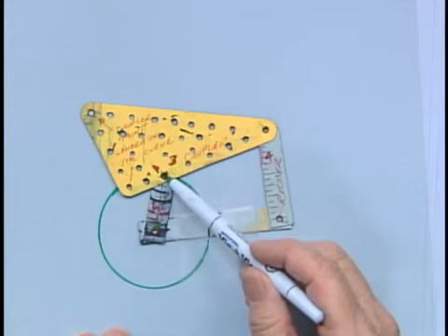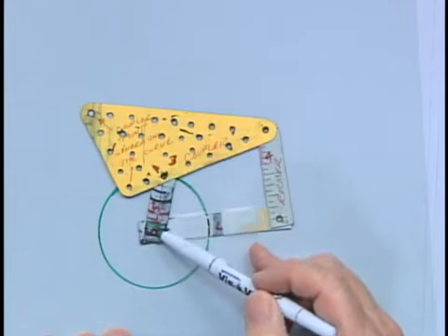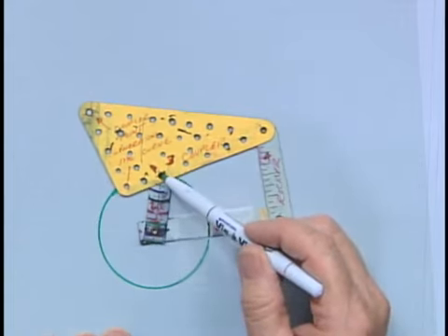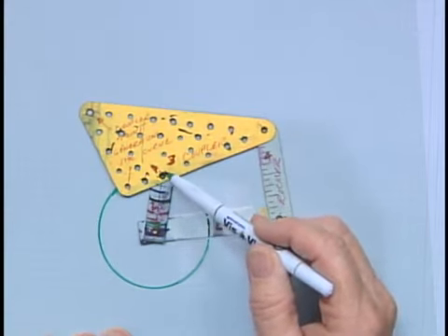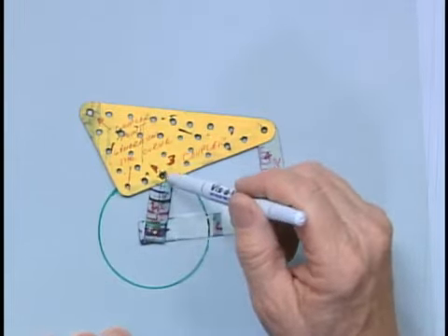As part of link 2, it's being forced to rotate in a circular arc about instance center 1, 2 down here. And thus, this is a degenerate coupler curve in our sense of 6th order curves. It's degenerated to 2nd order, or 2nd degree, I should say.